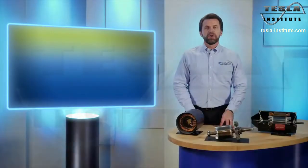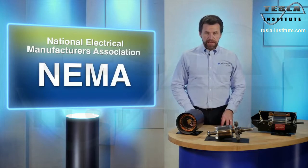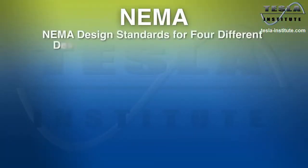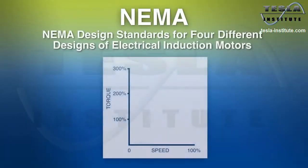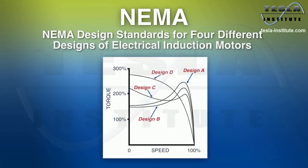Now let's discuss the NEMA design types and why they are important. An organization called the National Electrical Manufacturers Association, or NEMA, establishes technical standards for the manufacturing of electrical products. NEMA has established standards for 4 different designs of electrical induction motors, which are A, B, C, and D, respectively. Each standardized design has unique speed, torque, and slip capabilities depending on the work they perform.